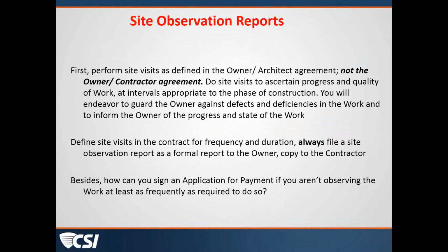Were there submittals? Yes, there were, but there weren't necessarily specific details about the termination, flashing, laps, overlaps within those submittals. They were very, very simple shop drawings that were cut through the window, and that was about it. And that's one of the most critical items to point out in this scenario. Gosh, I don't know if you can have enough details.